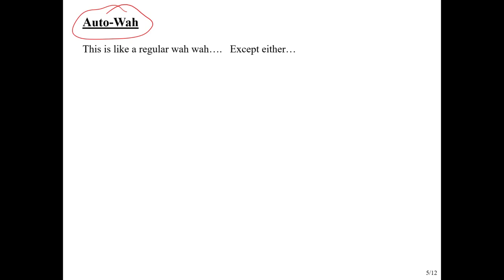The circuit is the same, except for how the resonant frequency is controlled. With the regular wah-wah pedal, the player rocks the pedal back and forth, perhaps in sync to the music, to the notes that they're playing. So it gives an awful lot of control. But here's the idea: you could just use an LFO to sweep that center frequency.